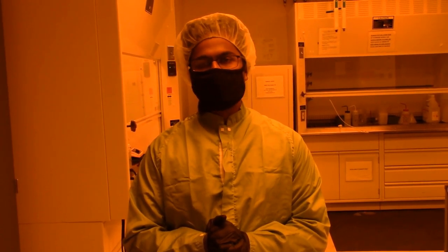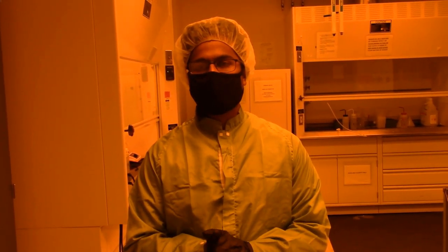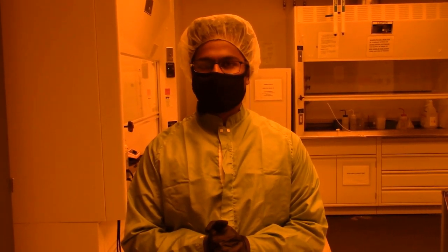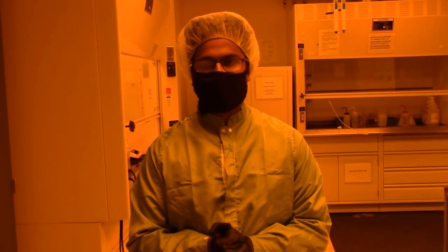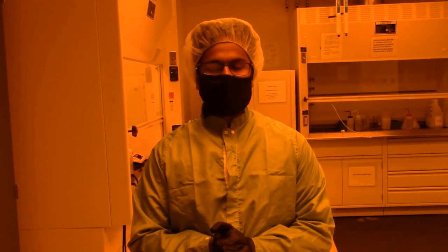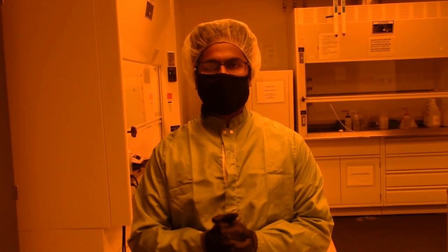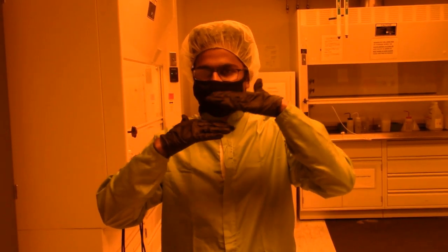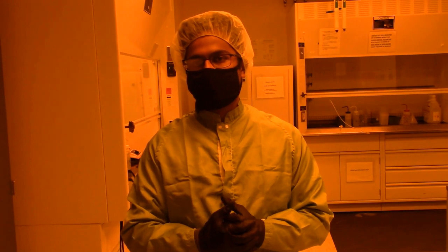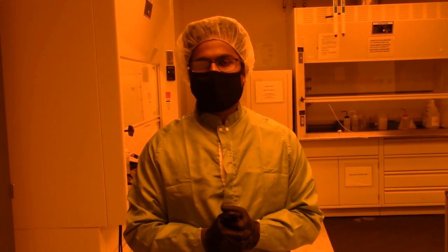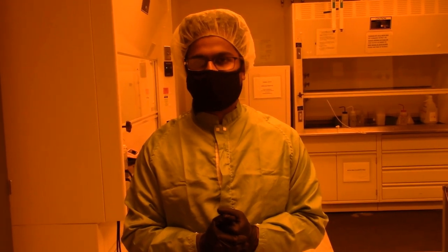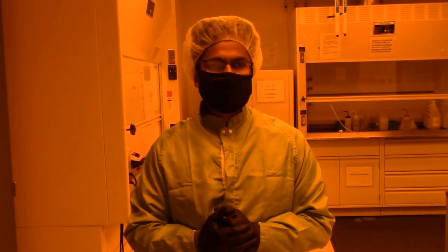In this lab, the first part of the lab, we'll be making a MOS capacitor. We'll start off with a silicon wafer, which is 2 inches in size and P-type. And we'll go ahead and make a metal oxide semiconductor structure to make a MOS capacitor that we will later on measure to characterize the MOS capacitor characteristics of the MOS device. So let's go on.